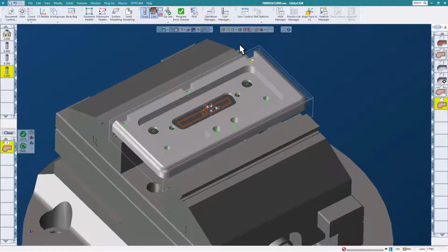Okay, so what we're going to do is use a macro to go ahead and machine a couple of these holes. You can also right mouse click on that when it's highlighted and grab the whole group. So at the bottom here, we say group 3. Then I'm going to go up here and say, go ahead and drill that for me. Now, this particular macro has some stuff we put in there just so I can see what's going on. In this case, it says, hey, that's the size of the hole, and by the way, you're done, because it happens pretty fast. We want to make sure that we're getting all the things we're getting.